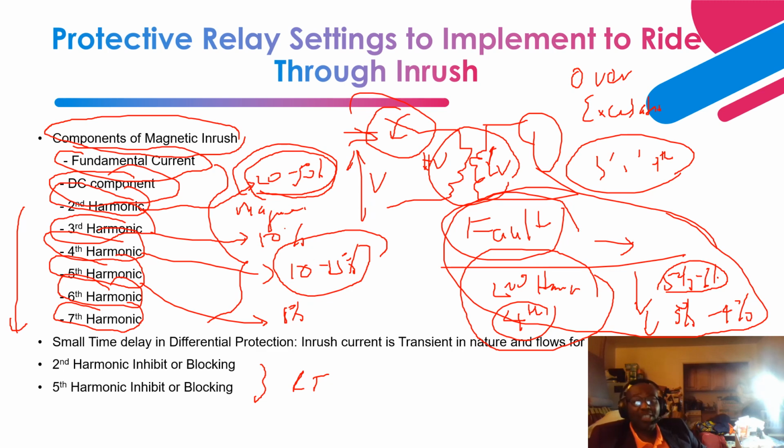I have to determine the allowable amount of overexcitation current due to odd harmonics that flows through the transformer during energization, and use it to distinguish between that and an actual overexcitation condition.